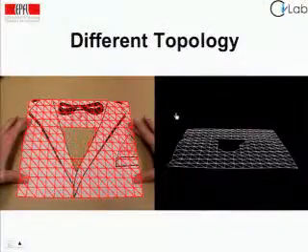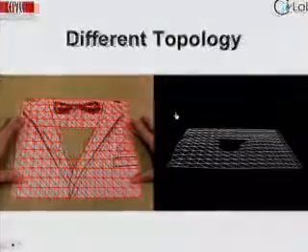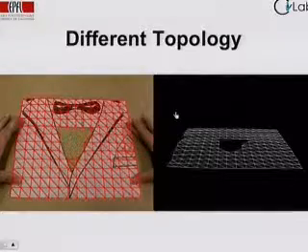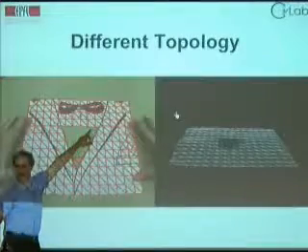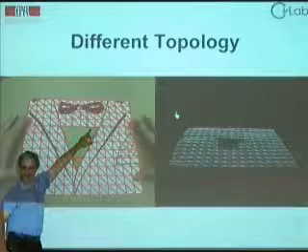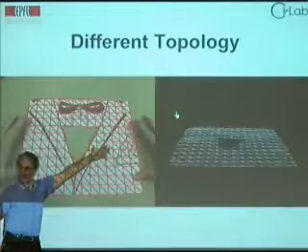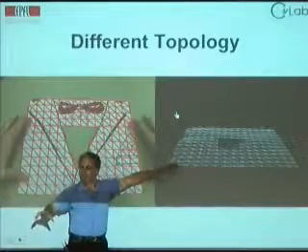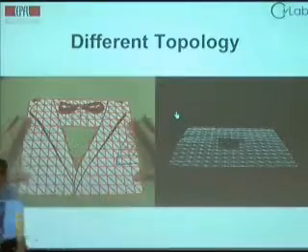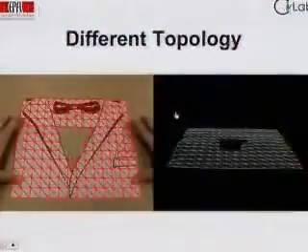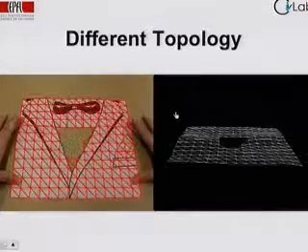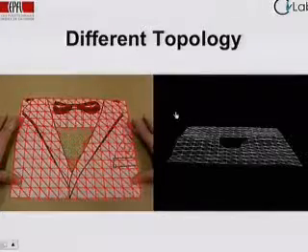And this speaks to your question. Your earlier question is, now let's take something made of the same material, but a different shape. Different shape because especially we've cut a hole in there. So we also changed the topology of the object. Doesn't matter, we can still compute our product of experts on this mesh. It's the same local experts, but the topology is different, so we get a different global model, and it works in this case as well. So that gets around having to learn a new model for every new object. We learn a model for a specific material.